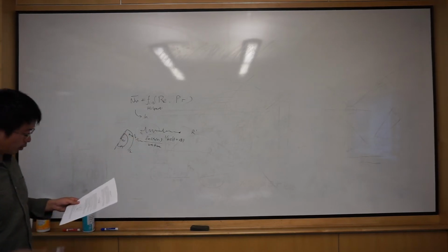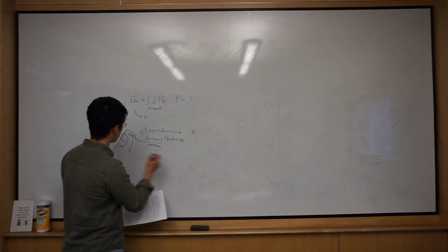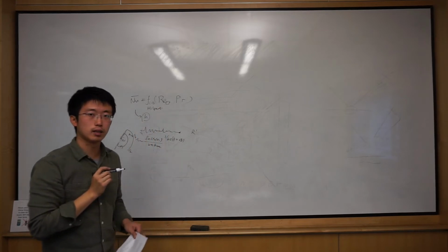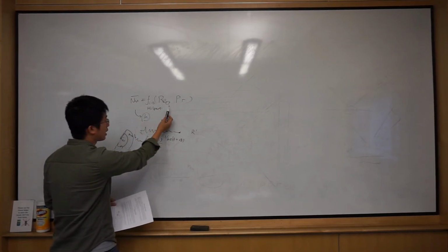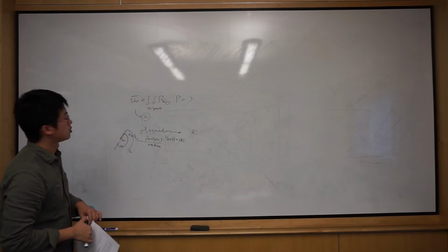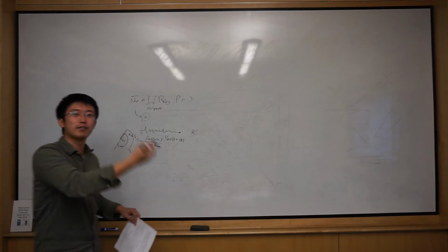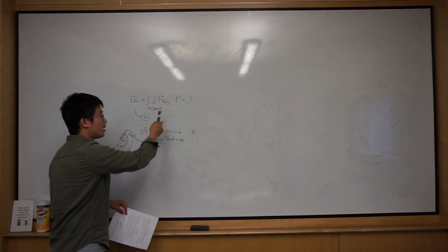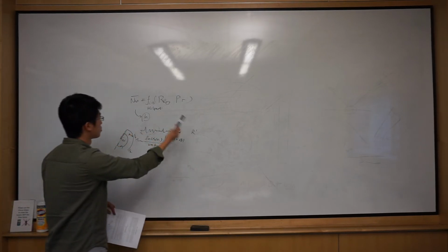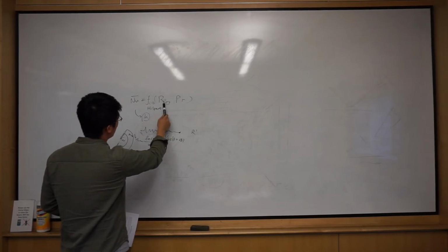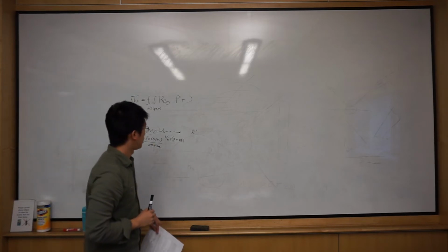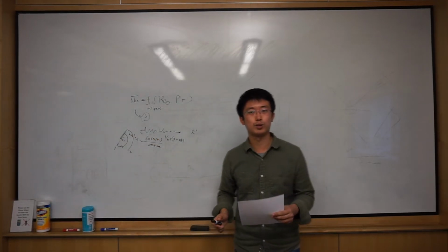Then you can repeat the calculation, but remember this h has a thickness hidden in it. So every time you need to recalculate the Reynolds number, and use the correct correlation. Since we gave you a reasonable range of thickness, you actually don't need to change the correlation. You can just use MATLAB to code it once, recalculate the Reynolds number, recalculate the Nusselt number and h, and put the h here. And that's about this question.